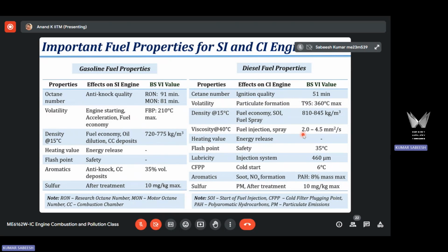We will discuss more about it in the second module, which is on emission formation. We will discuss the various mechanisms. One of the mechanisms is the spray characteristic in a diesel engine, because we know that the combustion event in a diesel engine is referred to as mixing limited combustion. How effectively you carry out fuel mixing carries a lot of significance for a diesel engine.